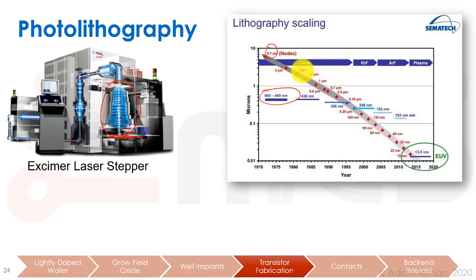And every once in a while, the wavelength of the laser was lowered, okay, but sometime in the mid 2000s or so, they reached this 193 nanometer laser, and maybe moved over here, as you can see, to wet. It was probably expected that this was going to go down to something else, but in fact, what was pretty common sense was that we were going to change to this EUV, which is 13.5 nanometers. Now, that's a big step.